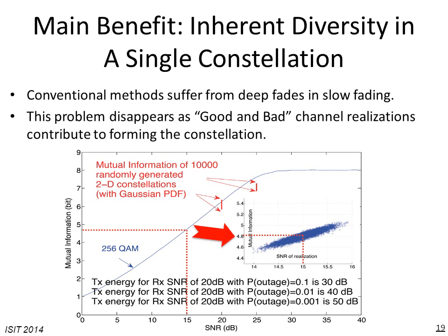Good channel condition means channel conditions with a higher gain, and bad refers to channel conditions with lower gain. So channel conditions with higher gain correspond to constellation points further away from the origin, and likewise channel conditions with low gain correspond to constellation points closer to the origin, which we need anyway. Like in any modulation, for example a 256 QAM, we have some constellation points that are closer to the origin and some that are further away on different shells of energy.